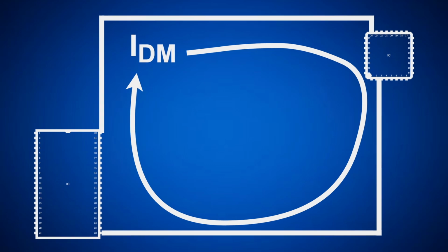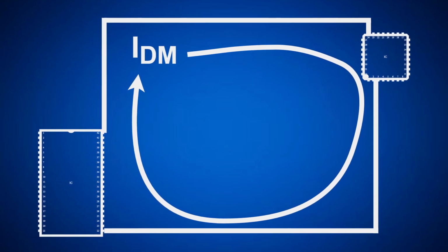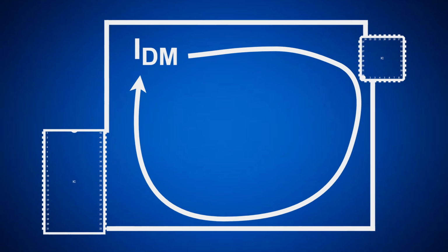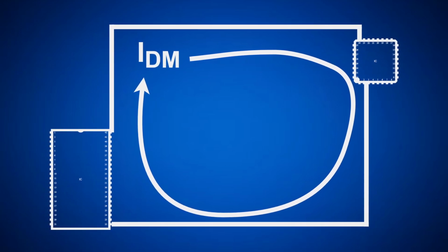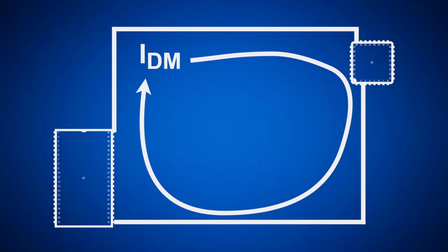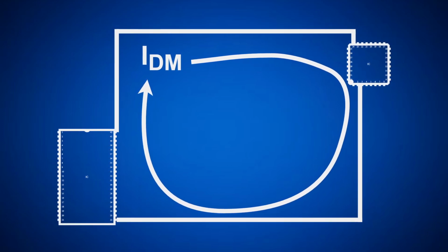So for the PCB layout, there are two main strategies you can employ to reduce your differential mode noise. The first one, of course, is minimizing the loop area. This means doing things like placing your components as close together as possible, routing the traces in such a way that they are as short as possible and your current loops are minimized. In my opinion, the best way you can go about this is to just prioritize the loops that you deem to be most critical. In other words, the circuits that you think will cause the most EMI problems, focus on those circuits and prioritize the proper PCB component placement and routing for those circuits first.